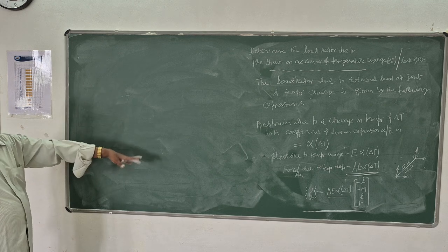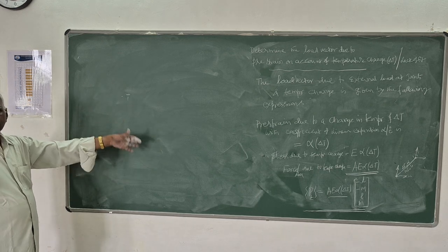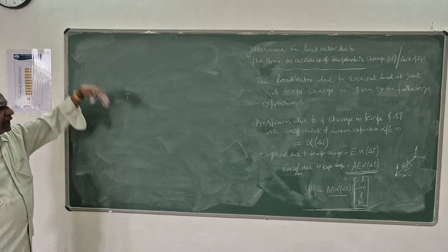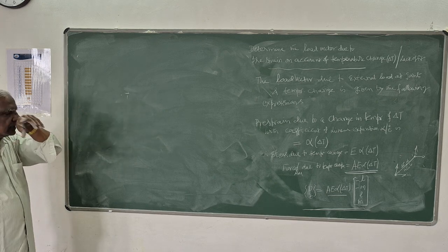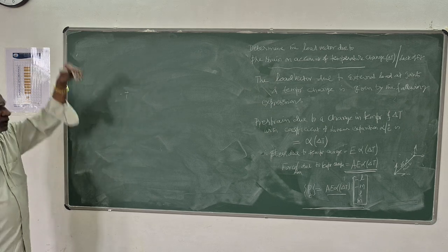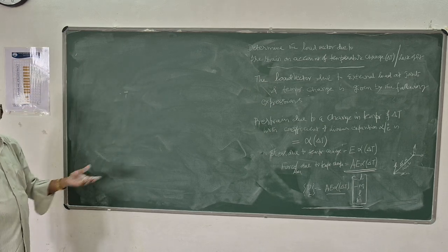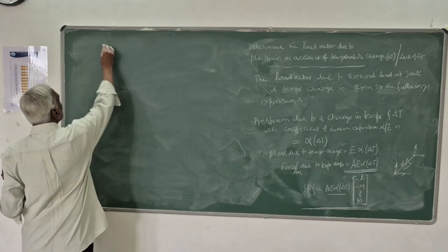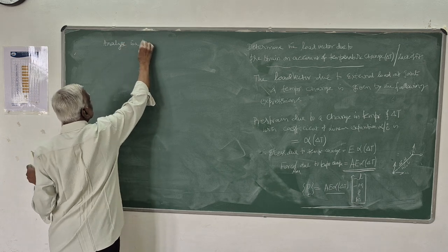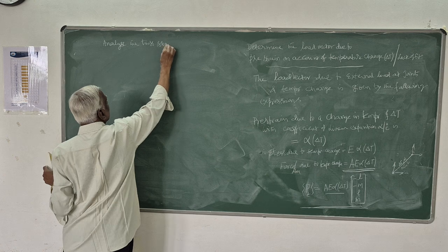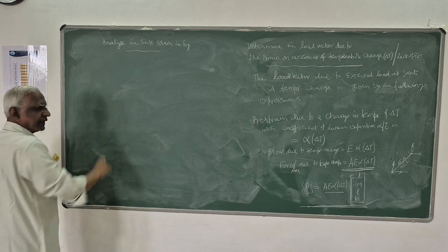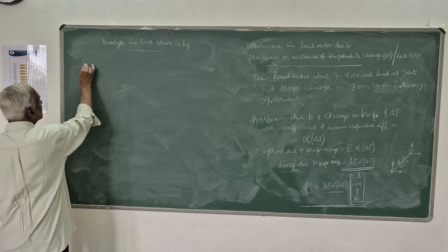How to derive the equation for stiffness matrix, how to take care of secondary pre-strain effects, all this. And for given load, the only thing you have to remember is if the loads are acting at the joints in the vertical direction, vertically up, you have to take positive. If it is given downward, you have to take negative. So, say, analyze the truss shown in figure by the finite element method.